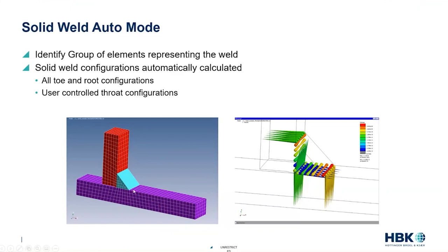any place that they attach with only one edge of the weld is fundamentally a stress discontinuity where the weld could crack. And so we'll automatically find, like this toe line here, and generate a series of locations and paths along that toe to do calculations on. The same thing for the upper toe connected to the red elements. When we get down to the root section, there's even more logic looking at multiple paths where we could see failures occur.